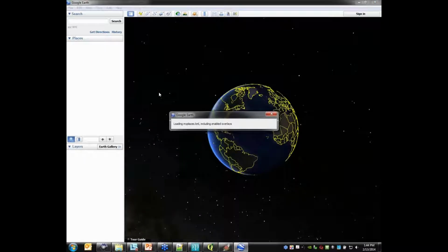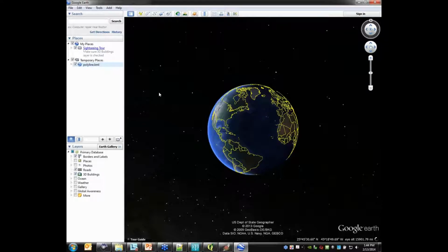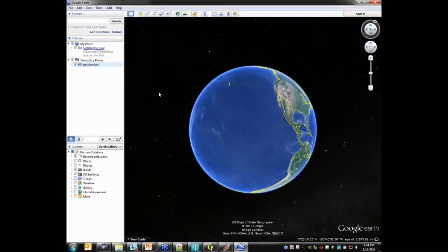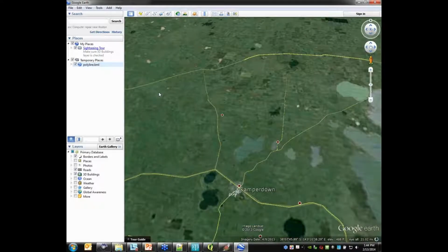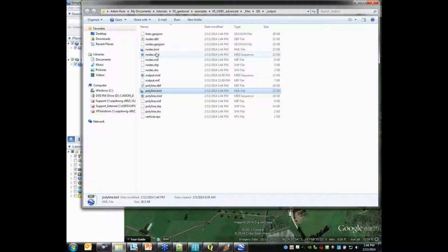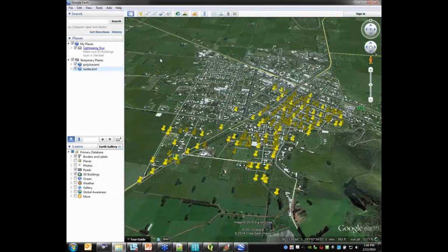Well, since I originally defined this as a map grid, I can easily convert that into latitude and longitude. And so you can see it shows up here, including a little bend. So there's the bend that we saw before. To make it easier to see, I'll go ahead and add the nodes. It generated all this data in about half a second. Also, just for interest's sake, you could certainly generate that as a shapefile or a MapInfo file.